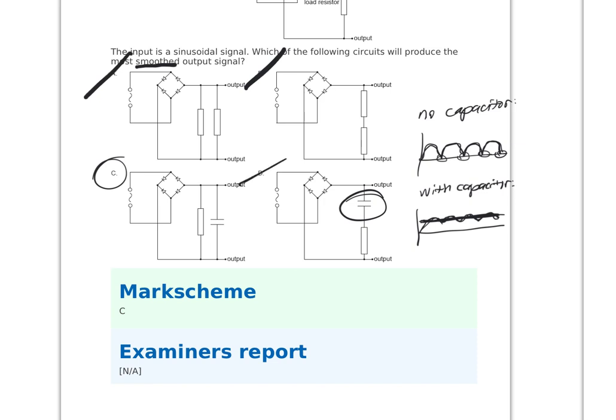And again, you just mentioned what the capacitor does. Why can't the capacitor be in series? Why must it be in parallel? Because if the capacitor is in series with the load, there will be no current flow while the capacitor is waiting to charge. That energy is going into the capacitor, and when the capacitor releases, then there will be a current flow. But while the capacitor is loading, there's a break in the circuit essentially, and you get no current flow.